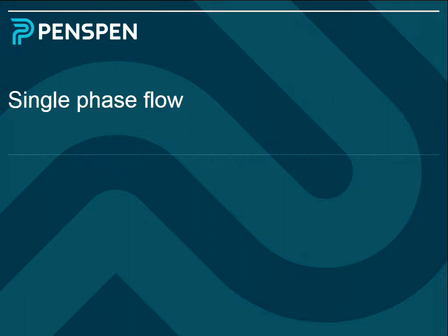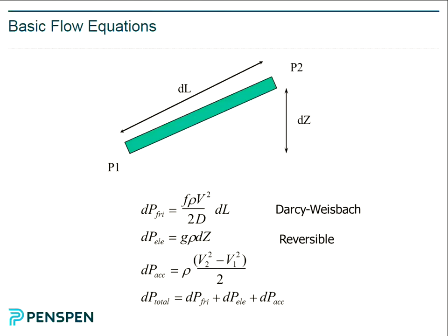So when you consider a single phase flow, irrespective of the variations, you only need to consider the difference between the inlet and the outlet. Even if it's gone up and down mountains, whatever, it's only the difference between the inlet and outlet that actually matters. Because whatever you do, you lose it, you get it back, you lose it, you get it back. The difference is important.